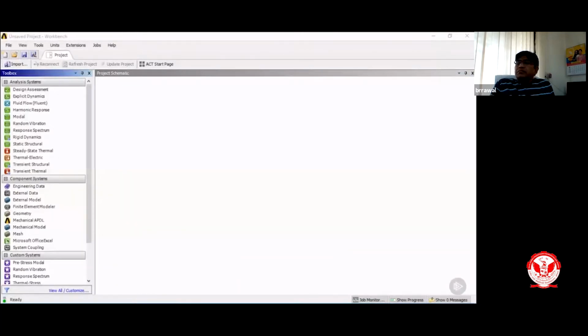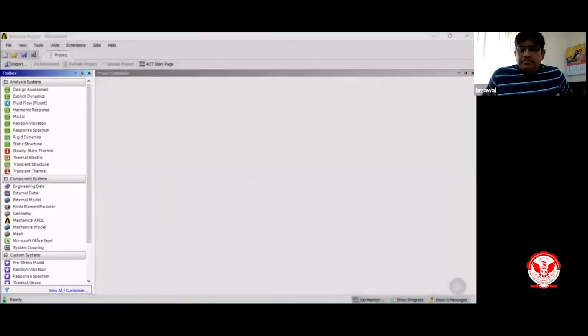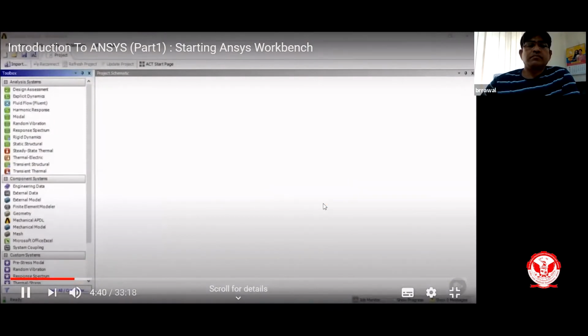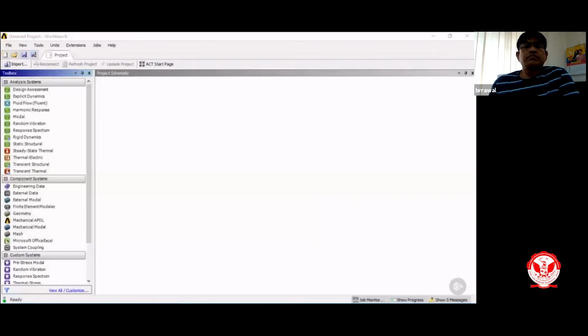When you open up a new project in ANSYS Workbench, it opens to the Project tab, which is just one of many tabs that can be opened in Workbench, but it's the main workspace in which you'll build your analysis. Like all tabs, the Project tab is made up of different views that can be reconfigured according to the information we want to see. By default, the Project tab has the Toolbox view and the Project Schematic view. The Toolbox view contains the types of data you can add to the Project Schematic. The systems are divided into categories, which can be expanded or collapsed in order to show or hide the systems in that category.